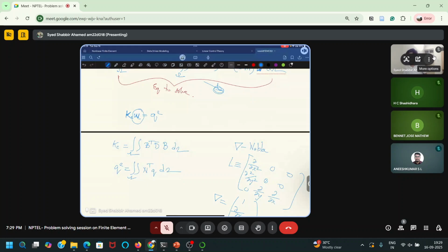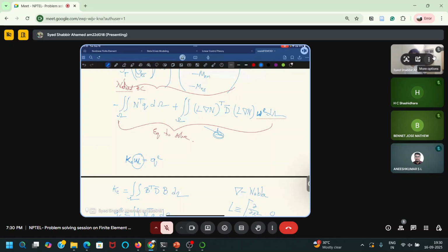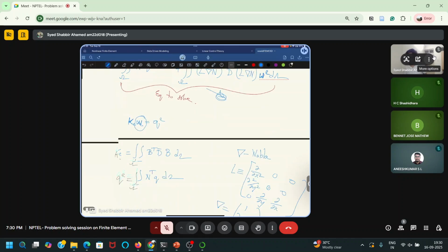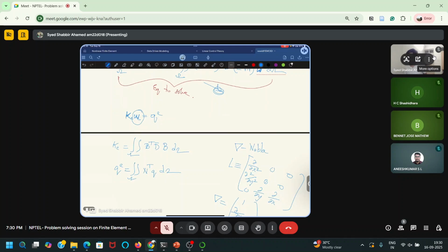So our end goal is to find out We. We already know how to derive the shape functions. If we know the shape functions, we can get K. Obviously, this is a simple thing now. You get the stiffness matrix. If you know the surface force Q, what is the load acting on the surface, then you can also get the nodal force on the plate element.